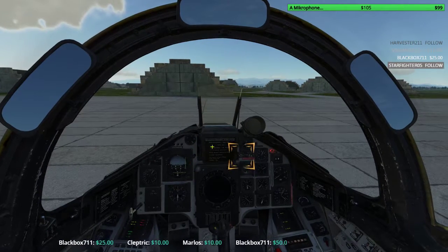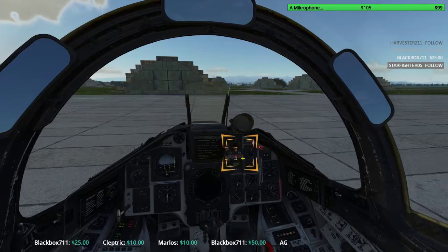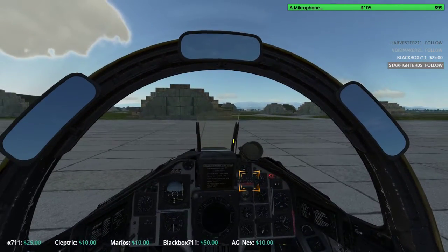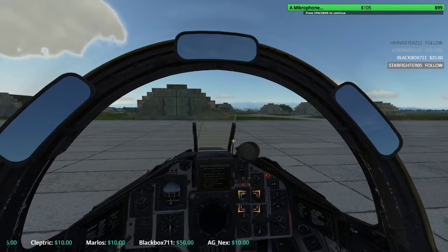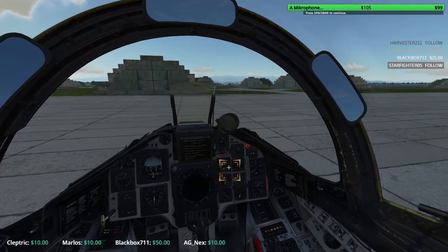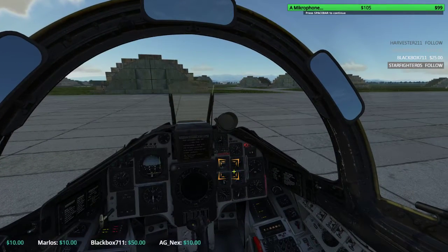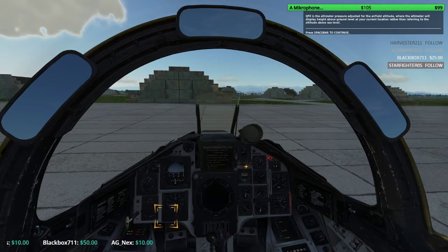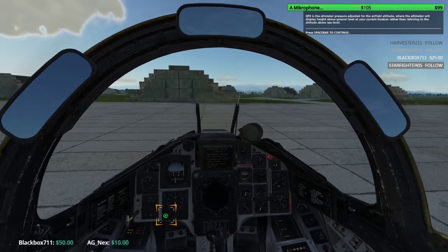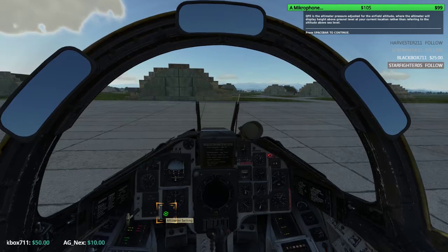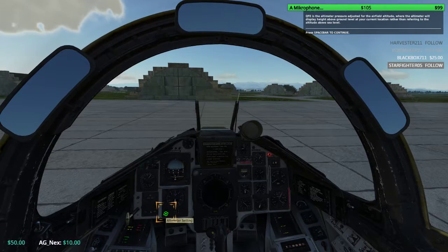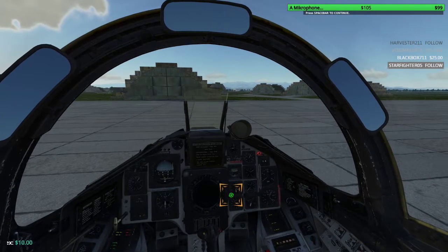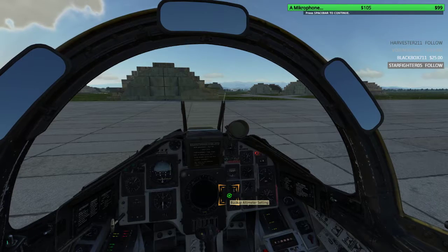Set the HUD slave switch to off. Set the CI HUD altitude source to barometric altitude. Pull the knob to uncage the backup artificial horizon. Now, set the main altimeter pressure. Turn the pressure setting knob until the altitude is displayed as 0 meters. Next, set the backup altimeter pressure. Turn the knob until the altitude is set to 0.